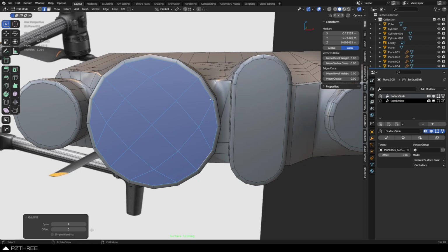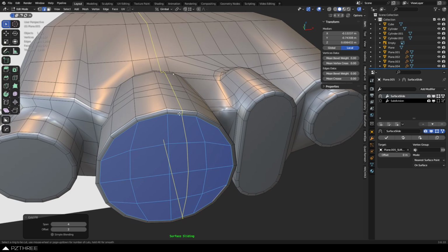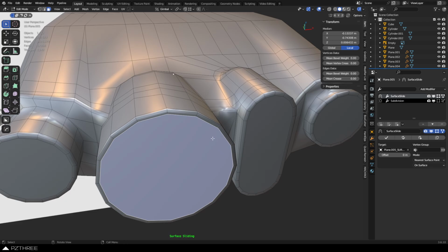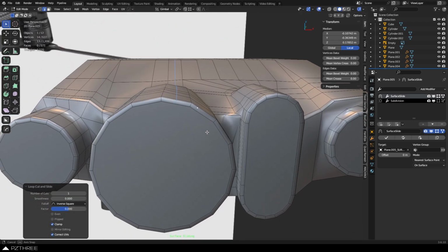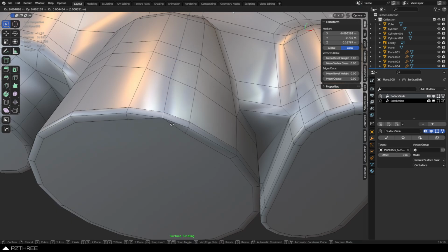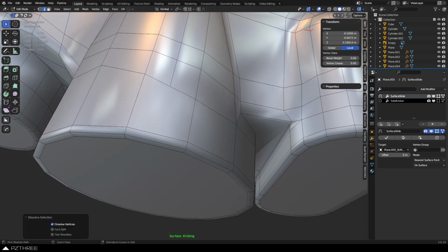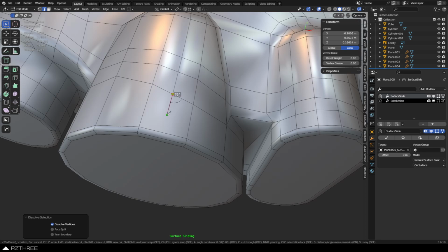And that's true, but here's the problem with that. If you do it right off the bat, you loop cut, it's going to send your loop all the way through it and around the model. I don't prefer that behavior. I'd rather leave an end for a bit, and then that way I can work up to it. And then I could say, I don't need this extra edge here because that's going to cause it to flatten out in that area. So I would probably try to figure out, do I need to do some kind of redirect in here before I get to that point or something?